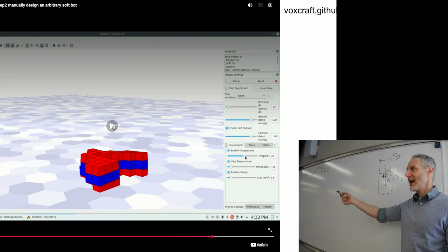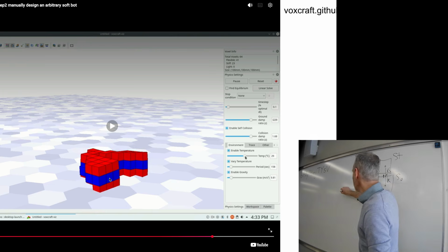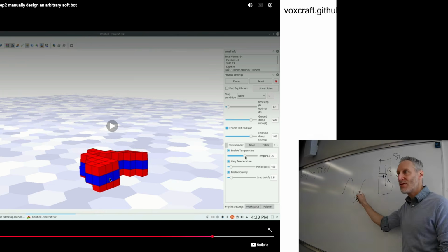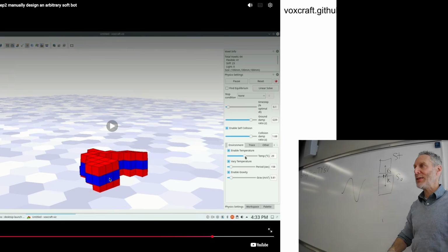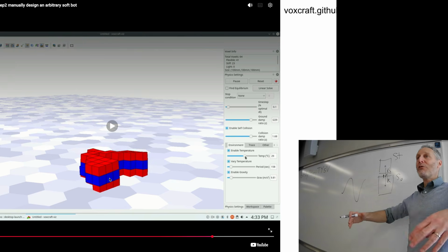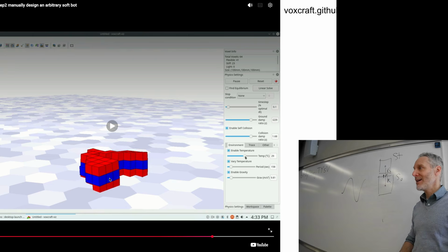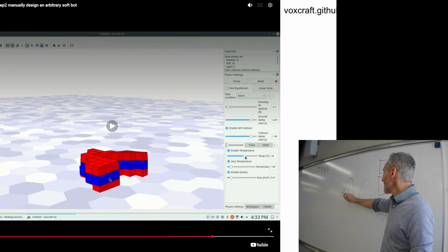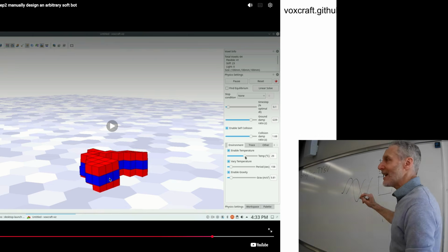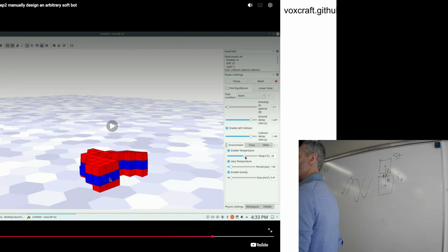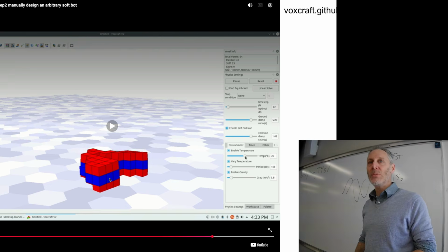Every motor is getting what signal? The same signal, right? I don't know how many beams there are inside this robot, but every beam is getting exactly this oscillation where everything is moving together. If I do that, I'm not going anywhere either, right? We need multiple signals that have phase offset. Once things start to oscillate, but oscillate at different phase offsets, then you get motion.